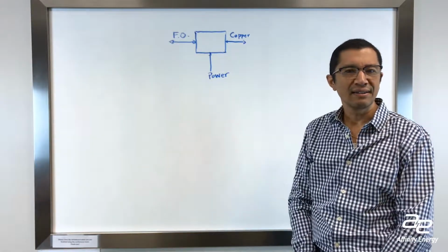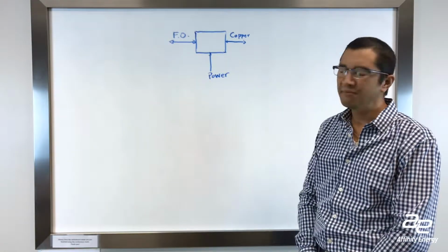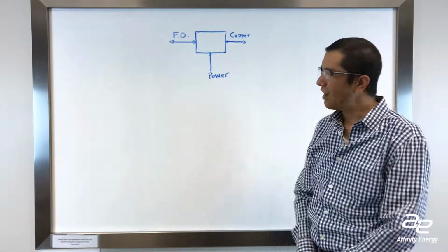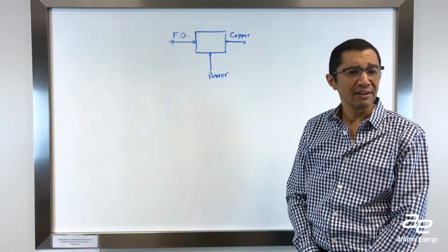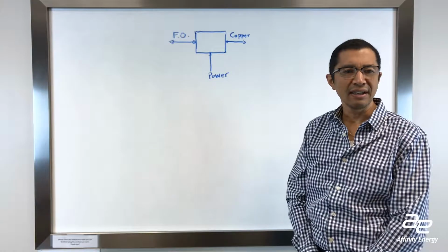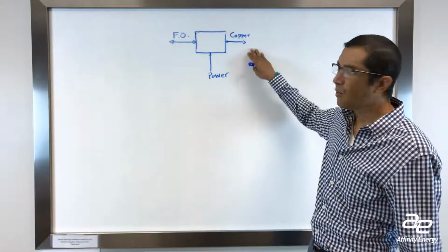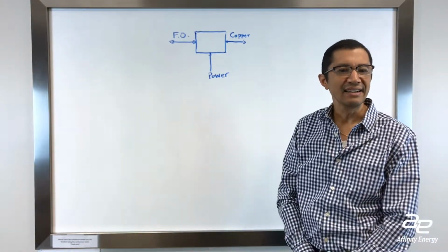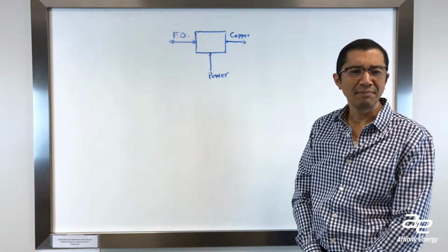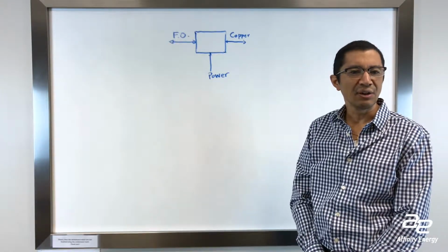One of the most sought after reasons why you would use a fiber media converter and fiber optic is you're concerned about distance. So typically there are limitations on copper, whether it be serial or Ethernet communications, on distances. For example, with Ethernet you can only typically go about 330 feet or 100 meters without requiring some other type of hardware in order to extend that distance. But fiber optic, depending on the type, whether it's single mode or multi-mode, you're talking about distances on the order of miles.